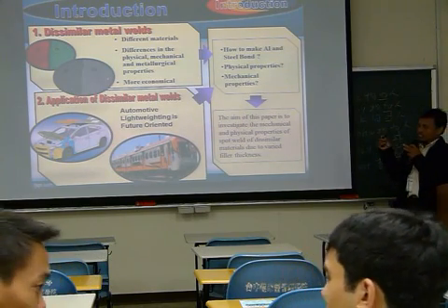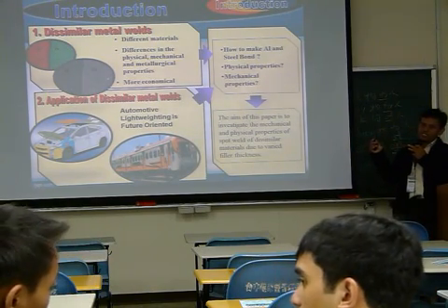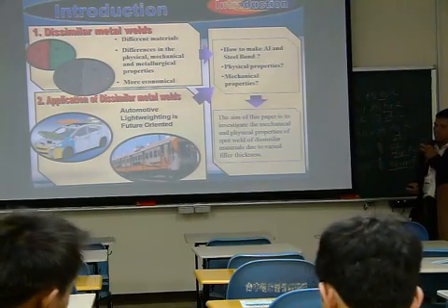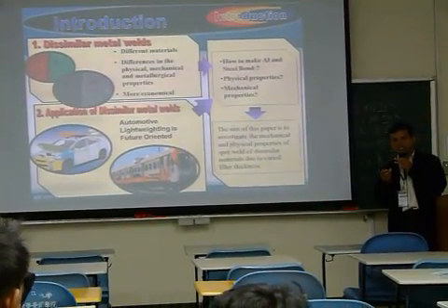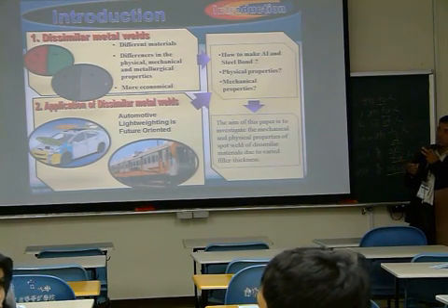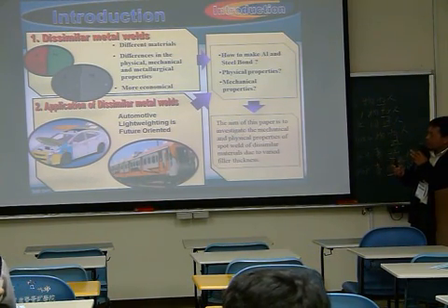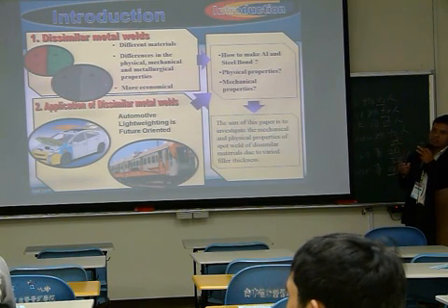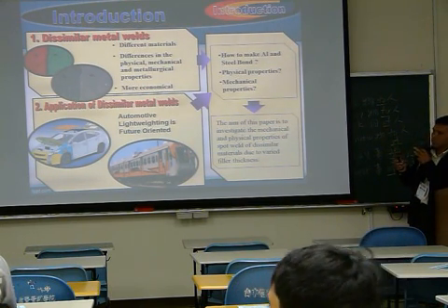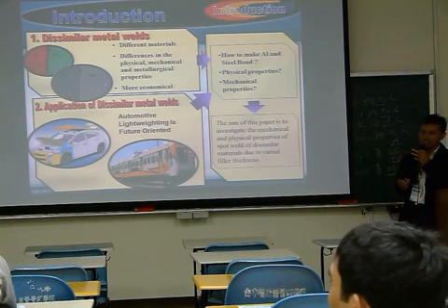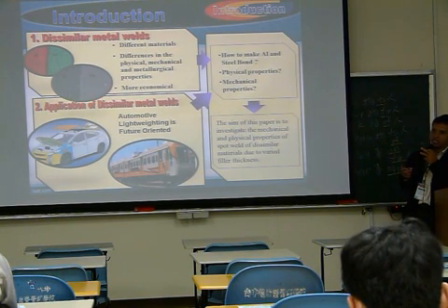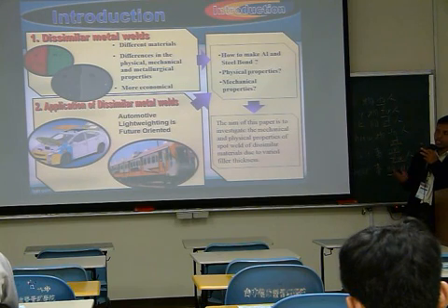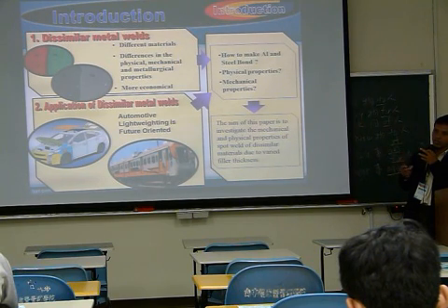I think it is the same case. Steel and aluminum are different materials, and they have different properties, like physical, mechanical, and metallurgical. And there is little solubility of aluminum in steel. Okay. So it is very difficult to join aluminum and steel.